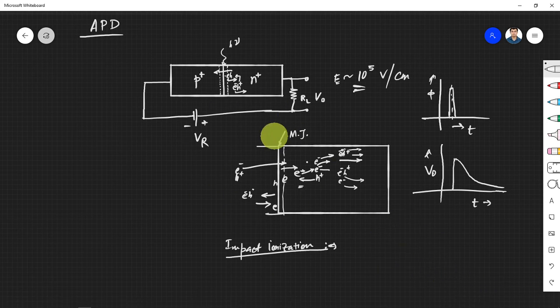So APD, you understood the advantage from normal PN junction, right? We have gain here, so we don't need to attach a pre-amplifier. In a photodiode or a photoconductor, the current we gain is in milliamperes or sometimes microamperes, so we cannot directly use this current, or carry the signal long distance.